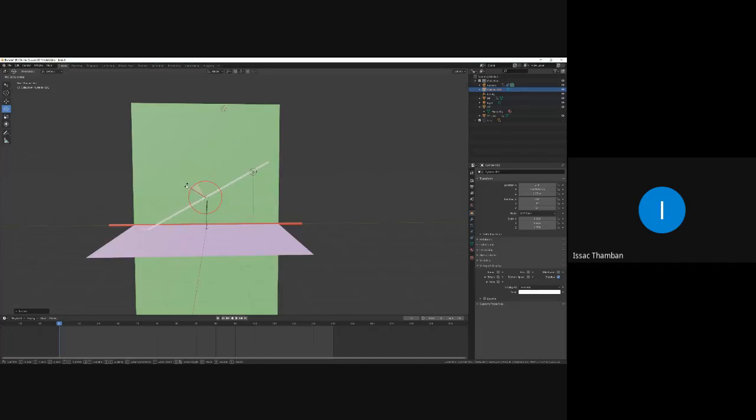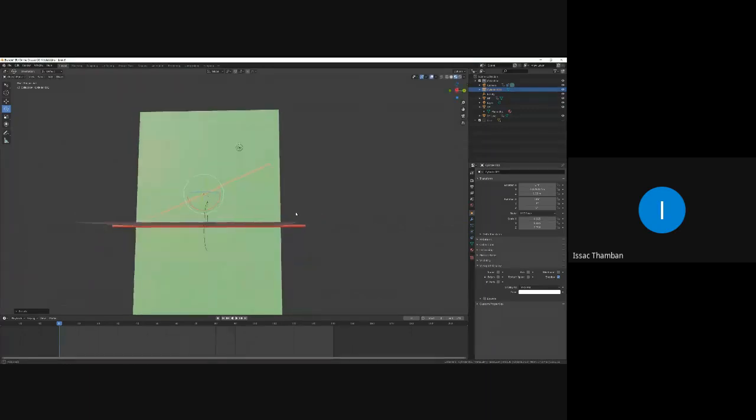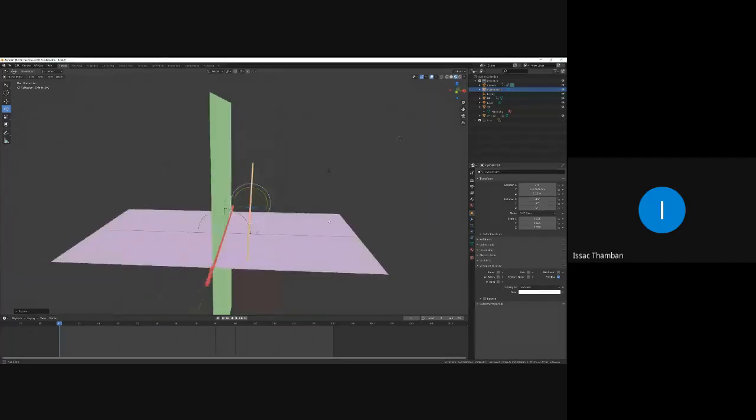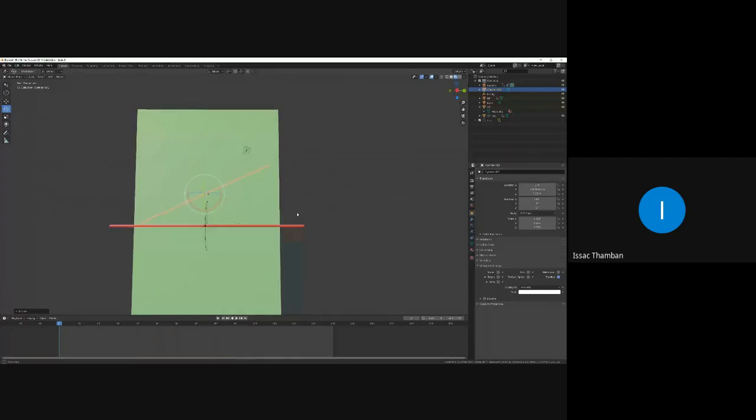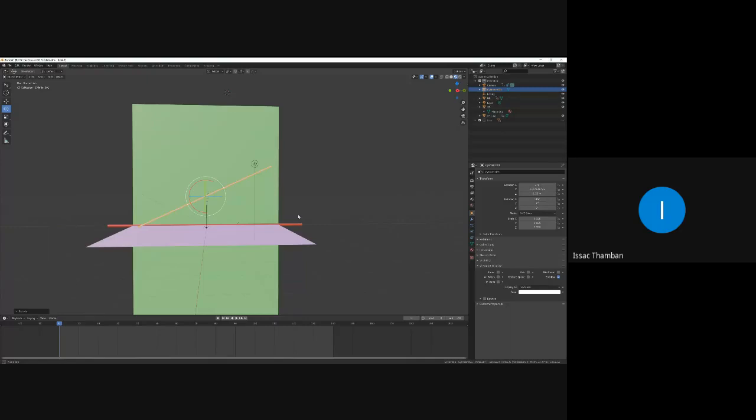Now it is around 45 degrees. So this is our first projection. Here the line is parallel to VP and inclined to ST by 45 degrees. We are tilting the line, pivoting the midpoint, not the first end.